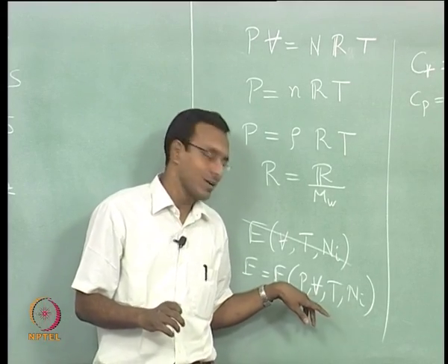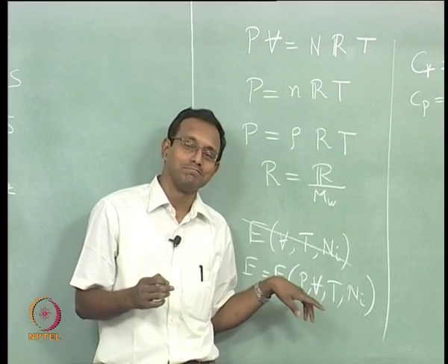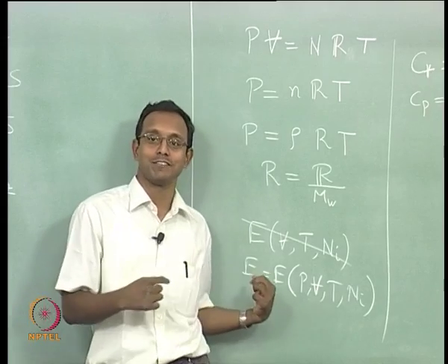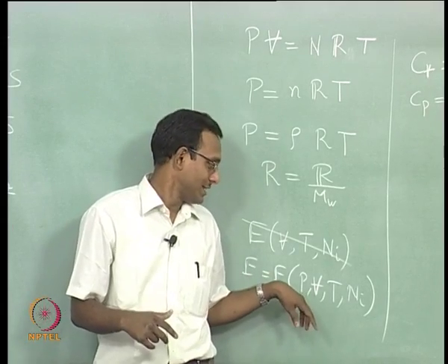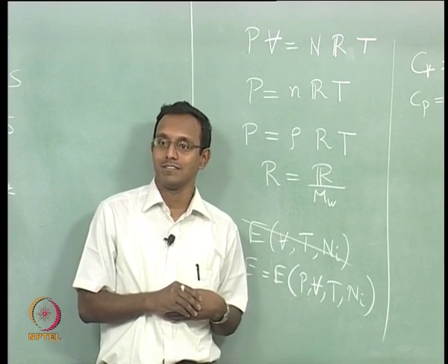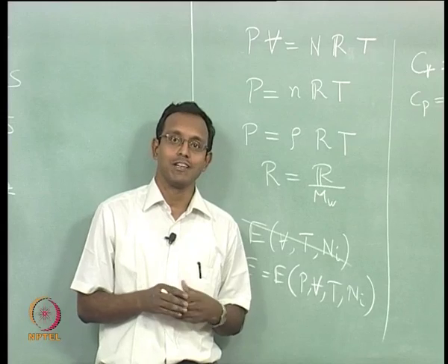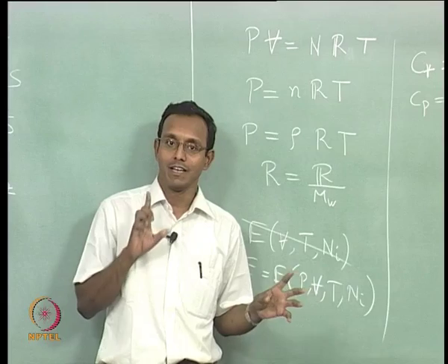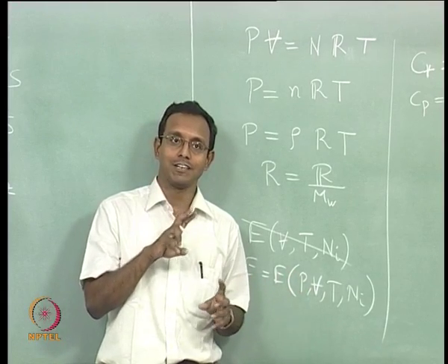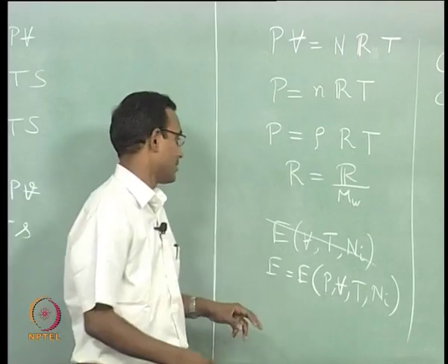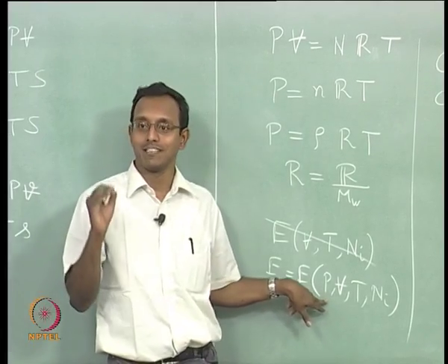Now, I am going to say volume, yes, it is there, that is my extensiveness of this quantity, we will keep it that way. Only thing is pressure, I do not want it to be a thing dependent on pressure currently. I am going to consider gases which are typically independent of pressure. The internal energy's relation with temperature is independent of pressure, that is all I am going to say. So, only those kinds of gases are called thermally perfect gases.